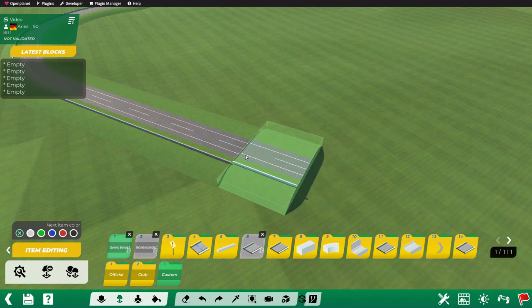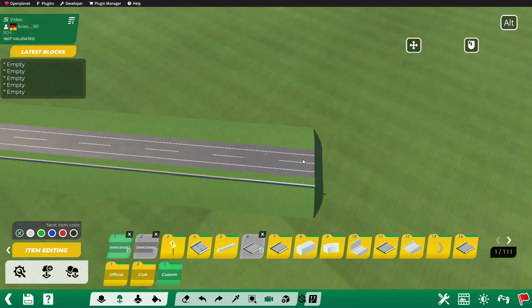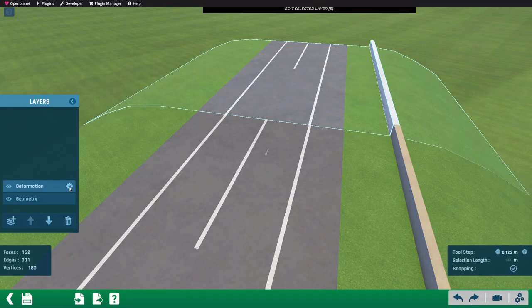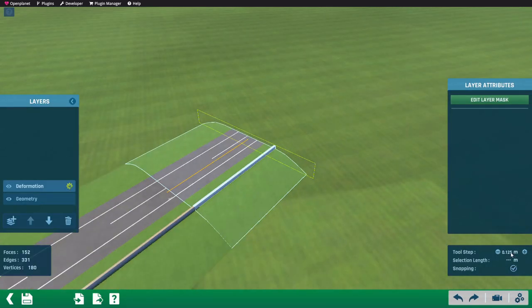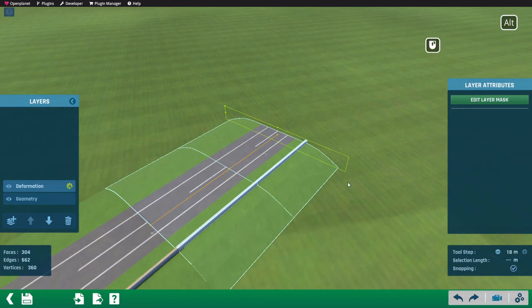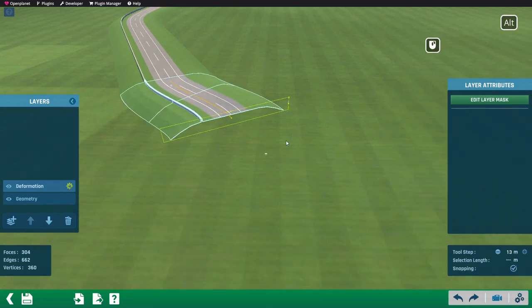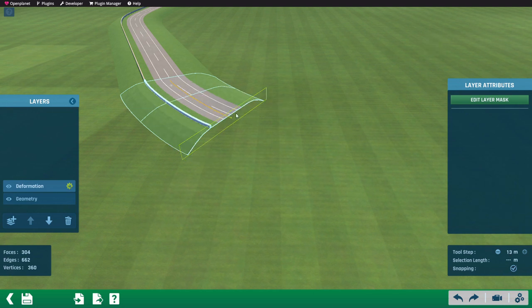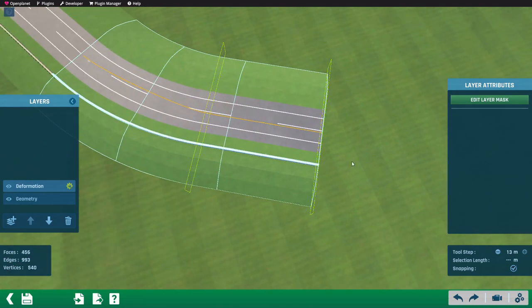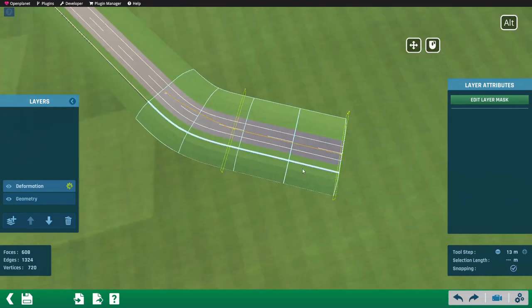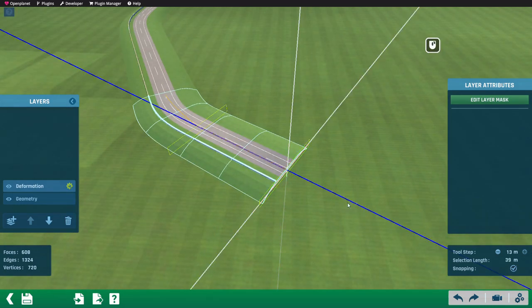Another possible attempt to solve this is to divide the deformation into smaller items, because the form of small angle turns is usually better with smaller items. Start a new item at the location you want the small angle turn to be. Create the turn and continue the deformation. You can notice that the form of the turn changes when you continue the spline, from too wide to correct to too tight. You can create the correct turn form by continuing the deformation to the right extent, and use again a new item from there on. You can exactly connect the items by using translation layers to position them.